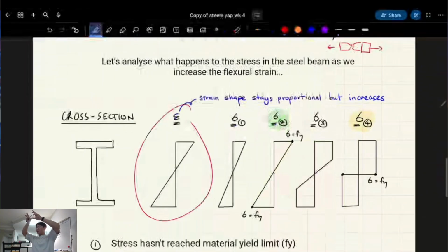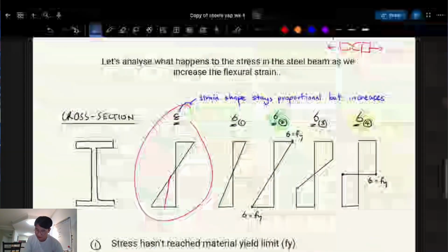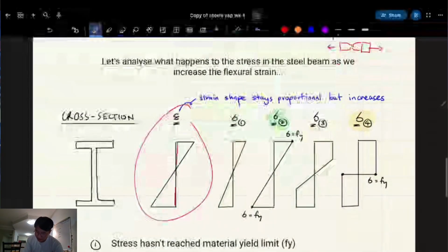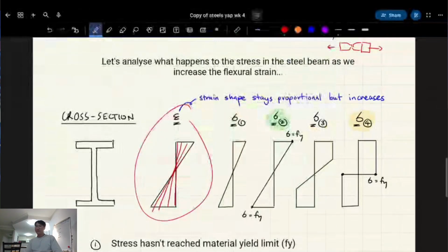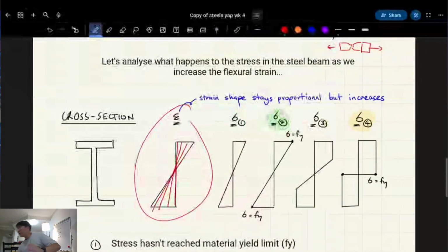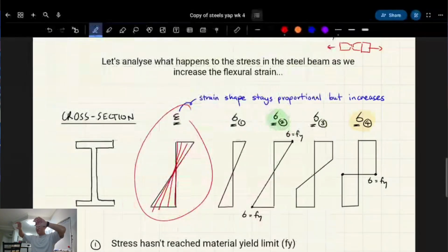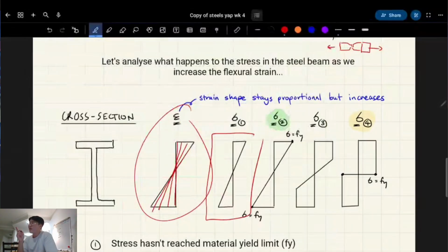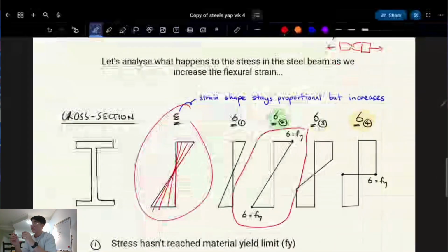Basically, as we increase this slope, it might start at 0, and then it goes like that, and like that. So what are we doing to it physically? The strain. As you keep straining it, we're adding more of that kind of racking pressure. That's what we're doing when we're straining it more. I'm increasing the amount of displacement. Originally it starts with an elastic response, and then here it's reached its yield limit on the edges, right?